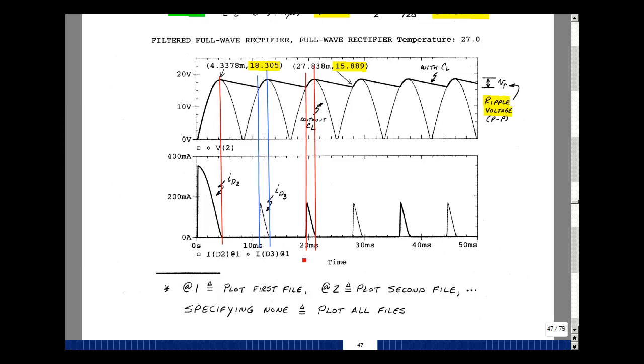And you can see here that these spikes are associated with part of the curve. And this part over here where the curve goes up, I get a spike of current in diode 3, and actually diode 1. And over here, when I get this spike, this is in diodes 2 and 4. And likewise over here, this is for diodes 2 and 4.